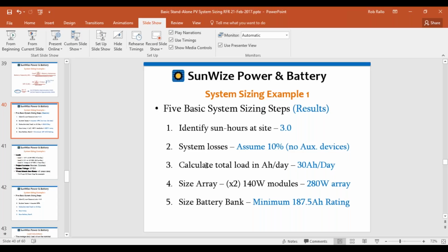Number one, usually that would work in your battery autonomy. So you're going to find in those locations in the country where you have a lot of snow, you're also going to have some bad weather. So generally, you're going to want to go to that 14-day battery for that. And because your solar array is also going to be at least a tilt of 45 degrees, generally higher, again, for those areas of the country where you get snow, you're probably going to be going to a 55 or even 65-degree tilt.